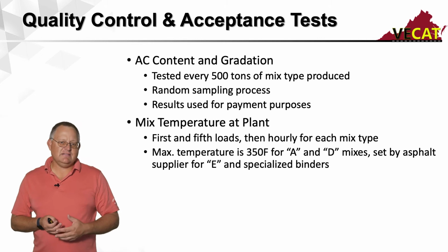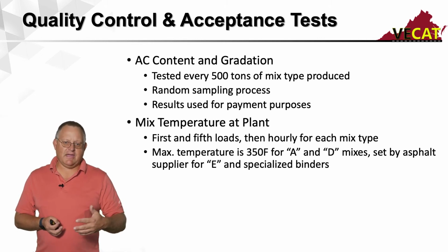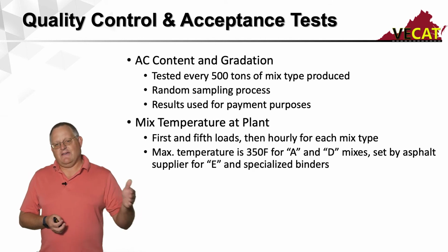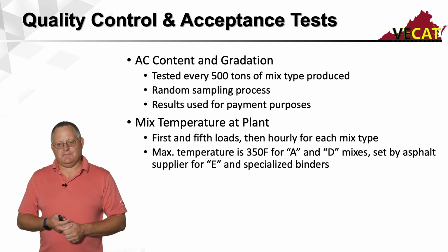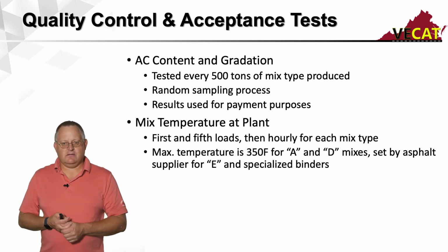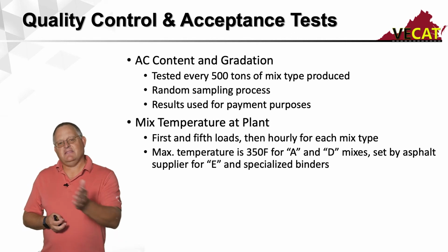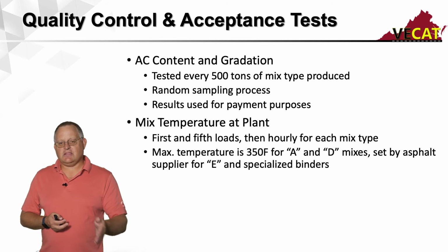We're also testing the mix at the plant. So if you look in the specs and in the test procedures, that first truck that we're getting ready to ship to the project, we're checking the temperature. If it's within spec, the 5th truck. If it's within spec, then every hour we're testing one of those trucks to check the plant temperature.